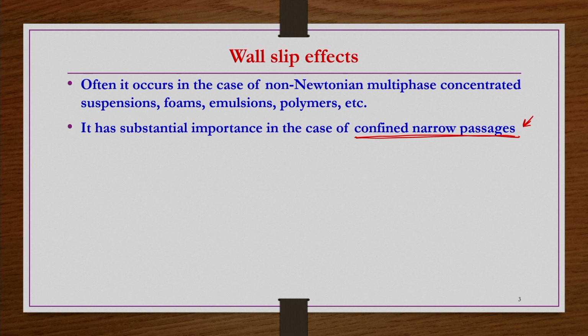It has been found that if you change the diameter, the wall slip plays a very important role in the rheological behavior, the overall flow equations, or the flow data that we are getting. So the wall slip effect is of substantial importance in the case of confined narrow passages. That means if the passage decreases, the wall slip effects become more and more significant.